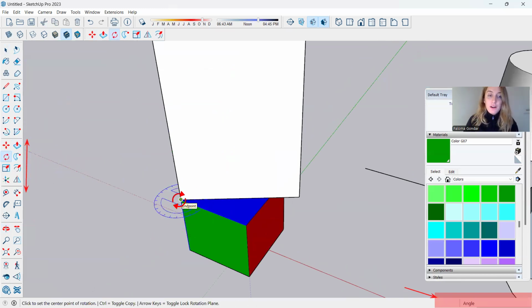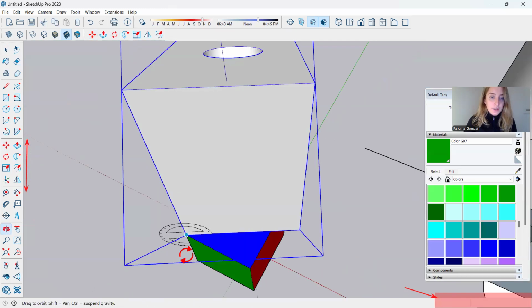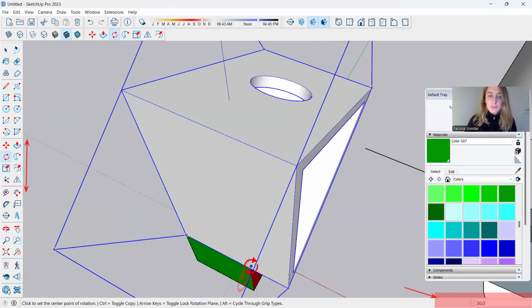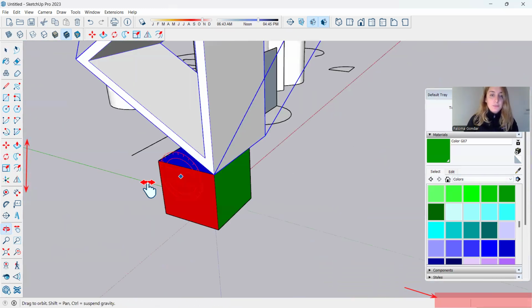Rotate. First, blue axis. I'm gonna select my edge of rotation first. First, select the element that we're gonna rotate. Second, rotate. Third, I'm gonna rotate in the blue axis. So we need to check here is my blue axis, and I set up that this is my edge of rotation. First left click, set up the edge of rotation. Second left click, I want this object to be aligned to this line. And that's it.